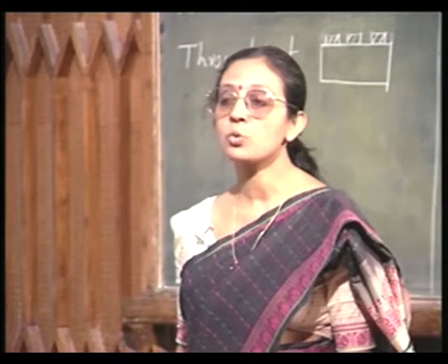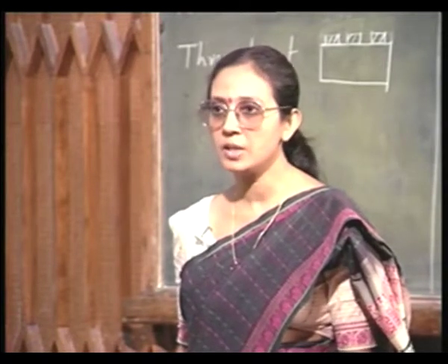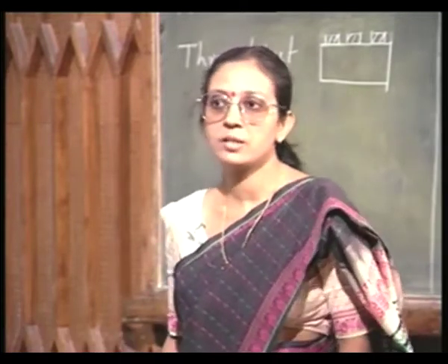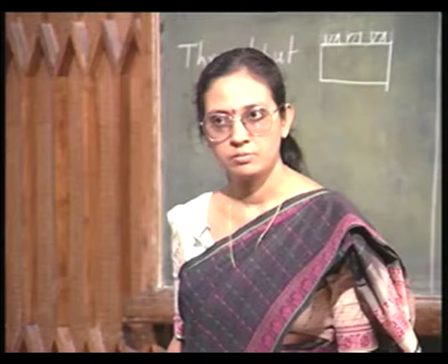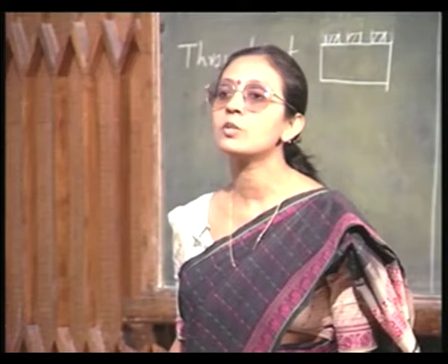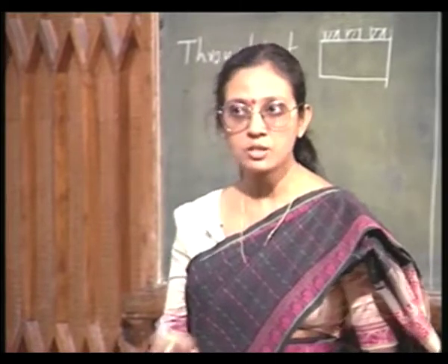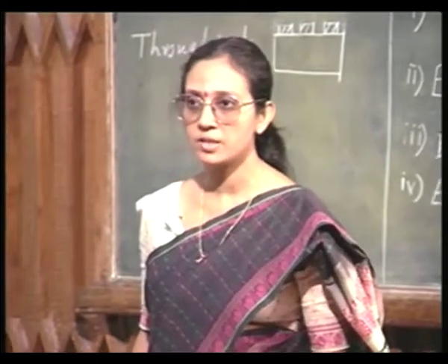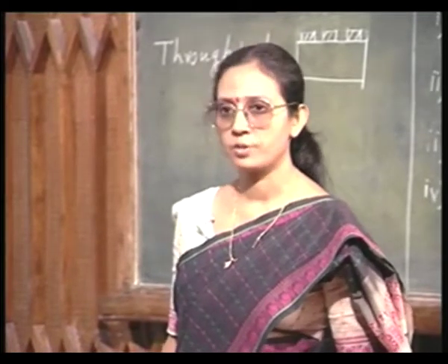So, resolution does not only mean the minimum feature size, it also means the precision with which the minimum feature size can be incorporated. You see, if your feature size is 10 micron, then obviously it does not matter whether it is 10 micron or 10.2 micron, but if it is 1 micron, then it matters. Then it becomes a 20% variation. So, the smaller your minimum feature size is, the greater is the need of having it very accurately. So, they are interrelated, the minimum feature size as well as the accuracy with which the minimum feature size can be transferred to the silicon wafer. That is a very important feature, resolution.